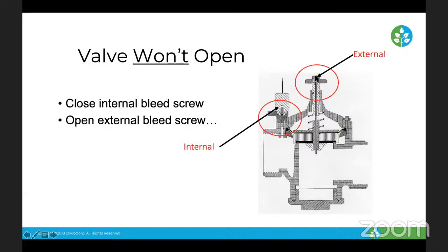And then if I turn my bleed screw and water comes out, so let's say for a couple seconds, then it slowly stops dripping and water stops coming out completely, and the sprinklers didn't come on, then I know that there's something hydraulically with the water coming in. Either it's clogged or a valve is off, something's off to where I don't have enough water for my irrigation valve.